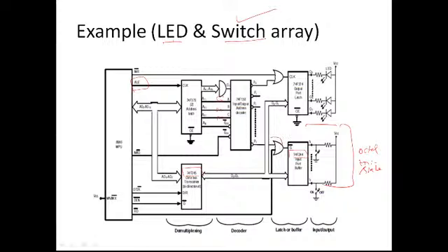The enable signal is connected from the output of the decoder logic. In this particular case, they have taken it from P0, through an OR gate. Look here, the other input of the OR gate is coming from read bar from the microprocessor. This is very important. It tells that this device will be enabled only when the processor is performing an I/O read operation. When an I/O write operation is taking place, this will be 1, so this will also go to 1 irrespective of the address.